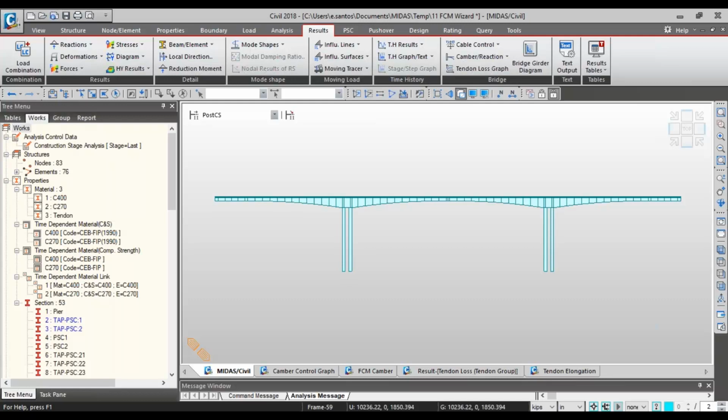cable-stayed bridges that we have available in the program. Then you have to tune the cable force using the cable force tuning, and then you can determine the initial pre-stressed force in the cable. This is the process: you basically find the initial cable pretension force. Then you perform the construction stage analysis. You verify the forces and adjust the pretensions.